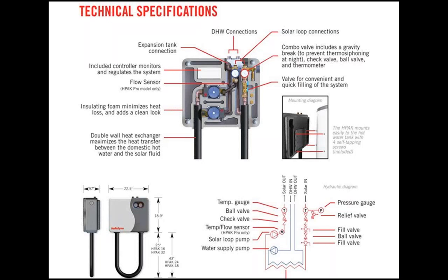Okay, so this is the appliance that I was talking about. These are the two pumps, and this loop here is a tube inside of a tube, so this is the heat exchanger. This comes with a couple of temperature gauges. It's got a flow meter, and one of these loops goes to the water tank. That's the potable water loop, and the other pump goes to the collector. So it does require two pumps, but it's a nice factory-built system, and so it's arguably more dependable than something that you would build together from a plumber.